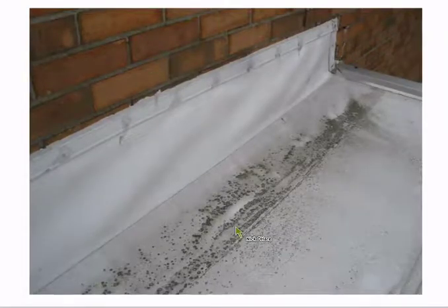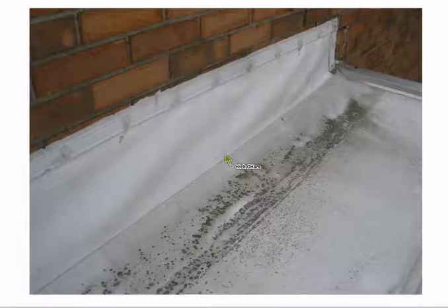I see this one all the time, Craig. We've got a decent looking, looks to me like a TPO roof coming up, being terminated. What are some maybe problematic areas that we're seeing here? Well, what I'm seeing here is the expansion type rawl plugs that hold that term bar in. A lot of roofing companies don't realize what that does to the substrate behind it. Every area they put one of those rawl plugs in, it's held in by expansion, which is expanding against those bricks. It's going to crack over time, allowing water to come into that roof system.